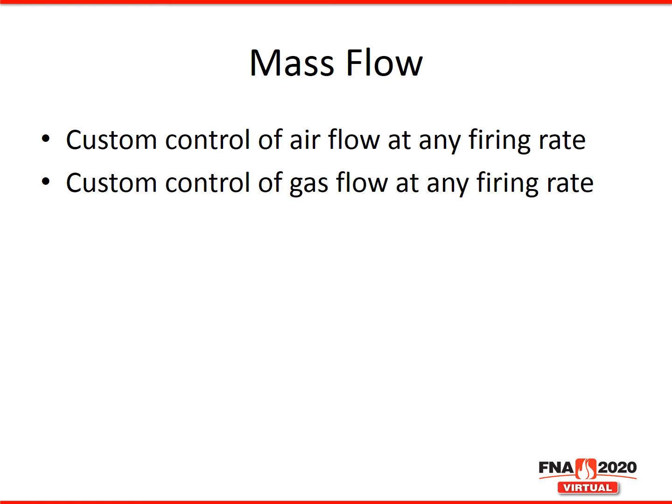In the other control schemes, we established a curve that resulted in air and gas flow based off of a firing rate. With a mass flow system, the flow can be customized by several different variables other than just firing rate.